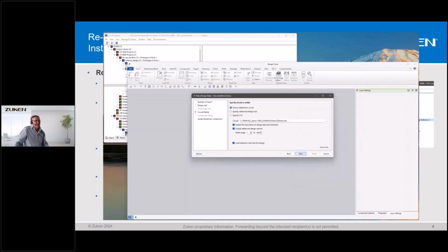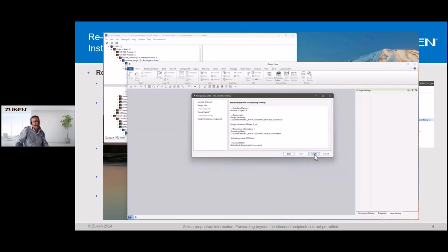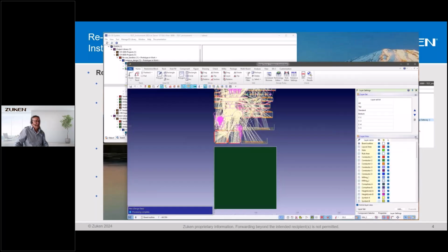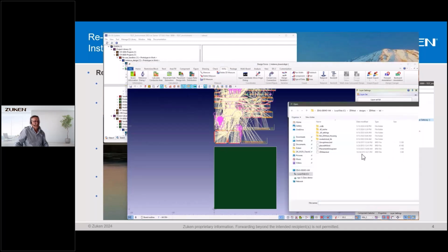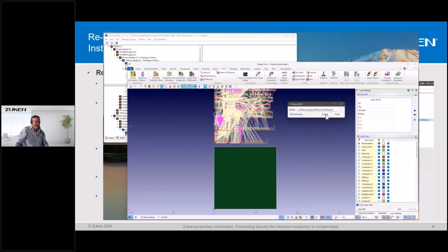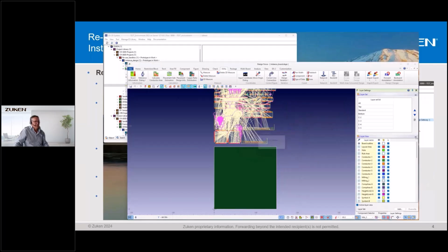The schematic is temporarily checked out just for netlist generation. But now, as this is done, the board is going to be generated with a default shape and a default board size. Again, to speed this up, I load an IDF file where a layout contour is available and the connectors as fixed components are pre-placed to get some kind of structure.